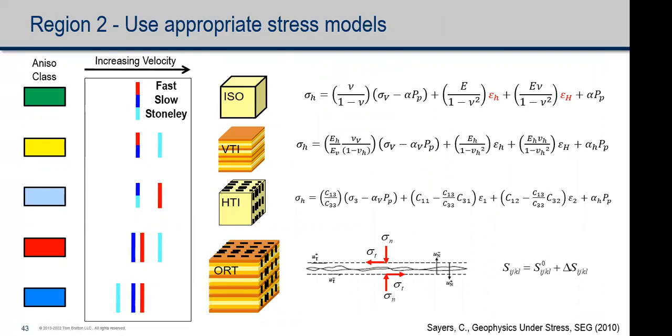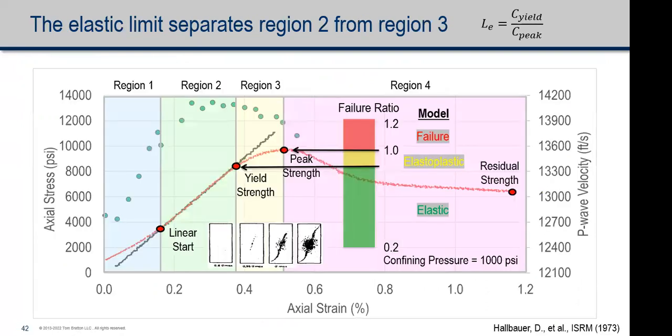So it's not quite elastic, because we all know that if you unload, and we have unloading loops and cycles during this elastic region too, the slope will be quite steeper. Absolutely. Which indicates that we never have a linear elastic response here in triaxial tests. We only have it when we unload the sample, and that's where we get this high stiffness.